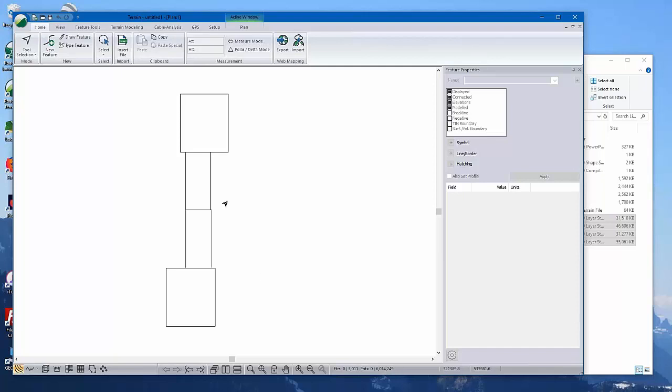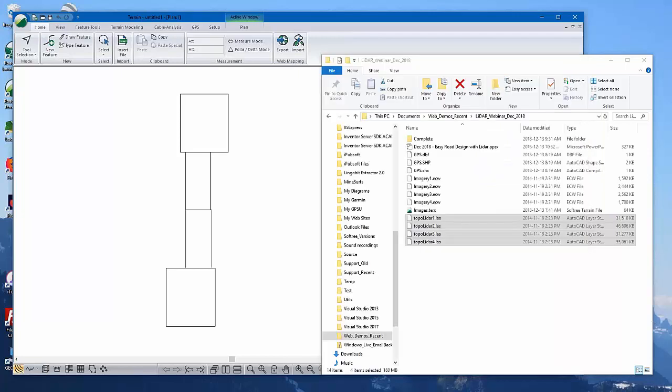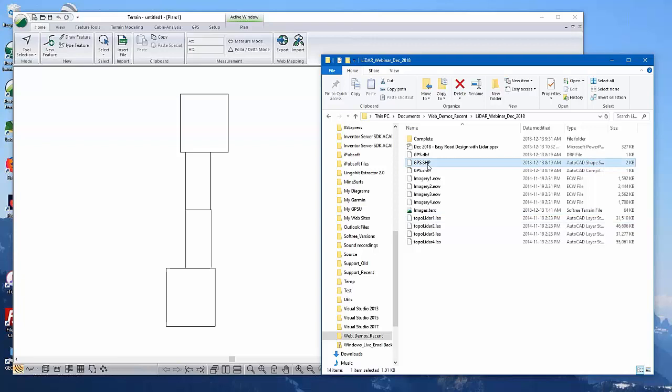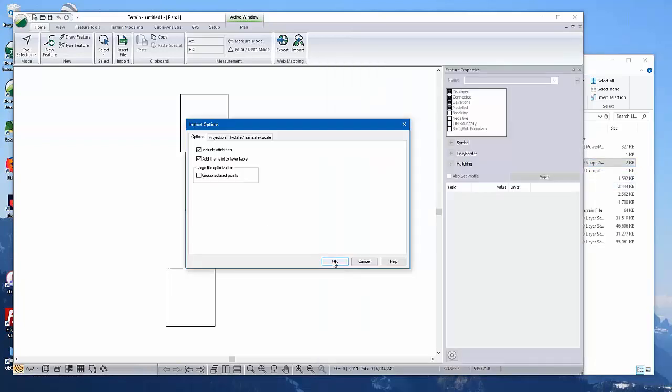Now, there, we've got the LiDAR data. We easily could work with this number of points, but to illustrate how I would thin them, I'm going to bring in a shapefile that's got some field work in it. And of course, if you're working with other data like shapefiles or GPX files, you want to be sure that it's in the same coordinate system as the LiDAR, whatever that might be.